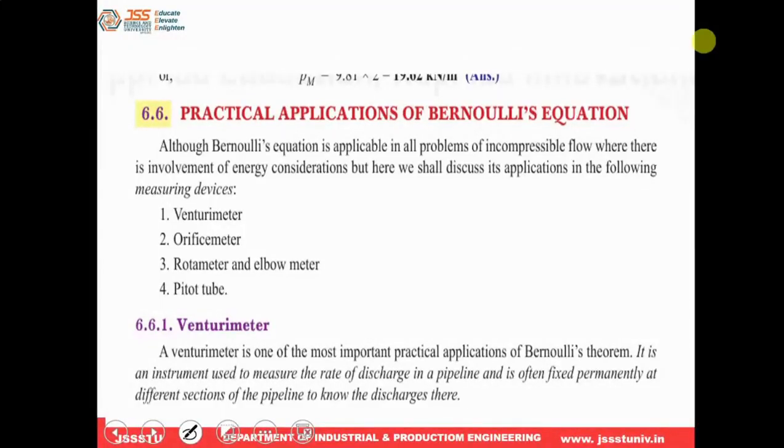So let's enter into the practical part. What is the practical application of Bernoulli's equation? Mainly we use this Bernoulli's equation for all types of incompressible fluid, and especially for flow measuring devices to measure the flow rate, like the Venturi meter, orifice meter, elbow meter, and pitot tube.